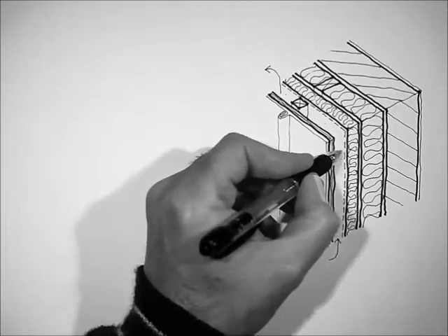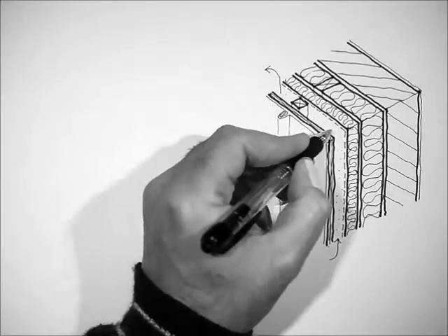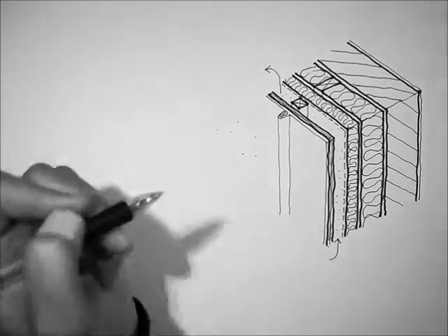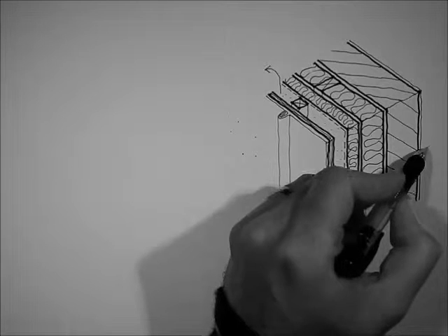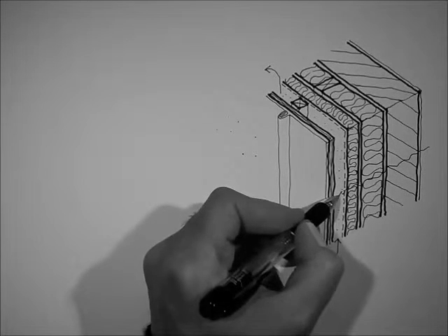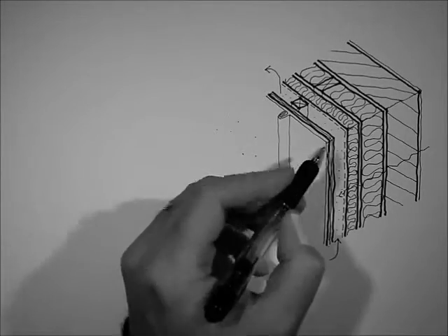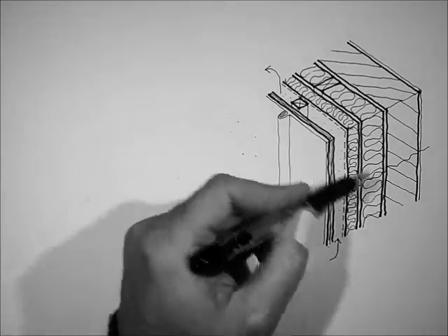What that means is that the air that is in this cavity is the same air that is outside. Any moisture that works its way through the construction into that zone ventilates away rather than condensing on any of the construction materials.